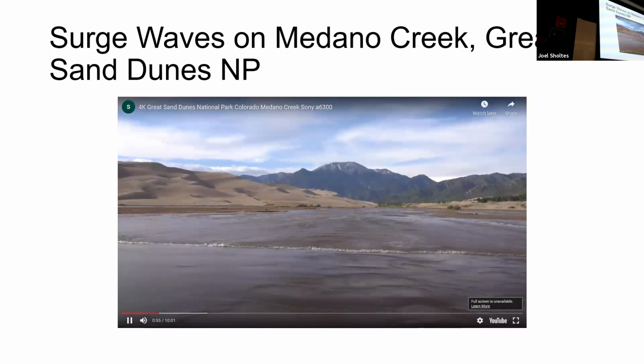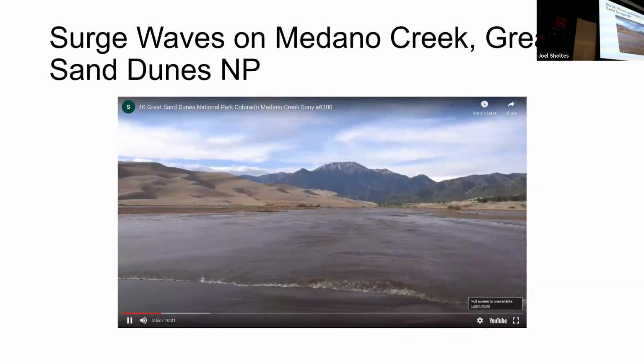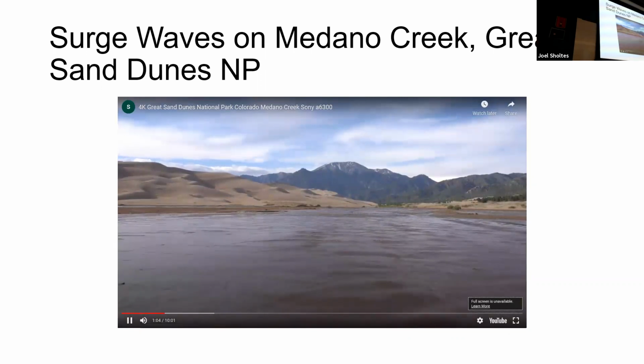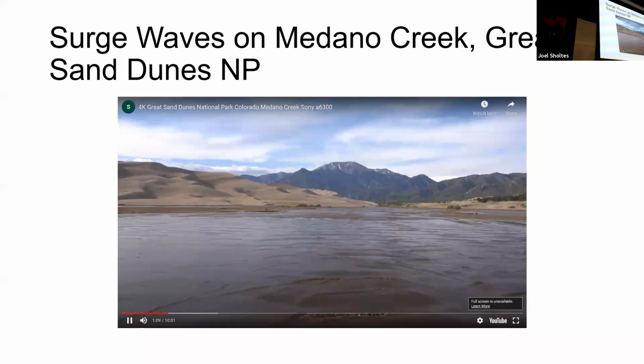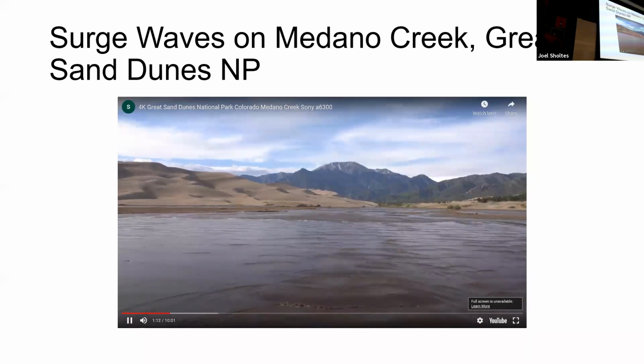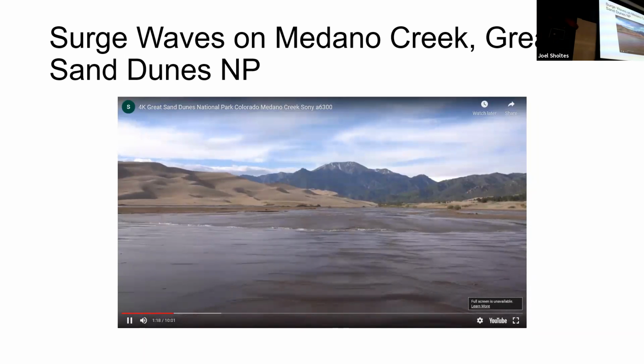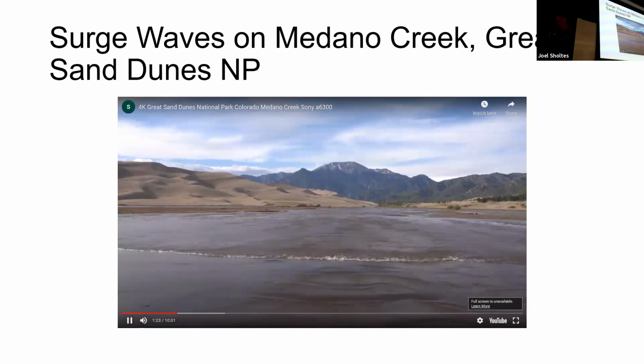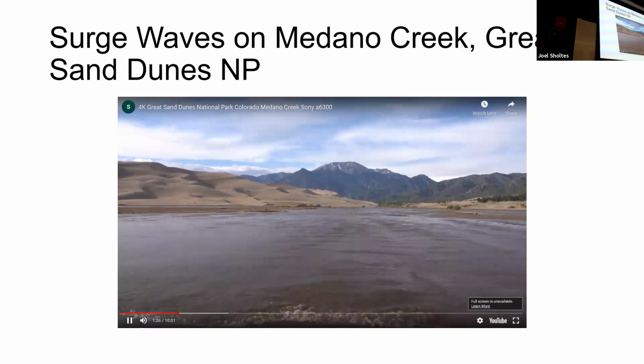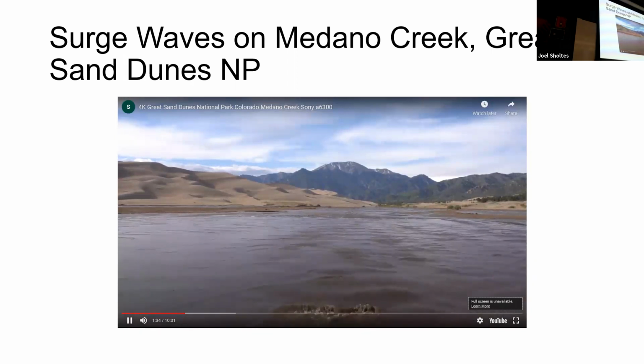Do you think the water is flowing at subcritical or supercritical conditions? You can imagine standing out here with your foot, right? If you were to stop and splash, do you think a wave is going to go upstream? Certainly not when this surge is passing, right? But even in between, it doesn't look super intense, but this is probably supercritical flow or near critical flow because it's steep enough that it wouldn't propagate a wave upstream. So these surges are passing through every so many seconds, and it's just continual.